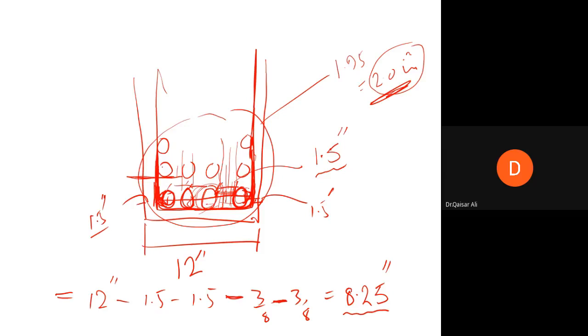Number 6 seems to be very convenient because 5 bars will be required, 3 bars can be placed in one layer and 2 on top of that. Okay, you can also try using more than 2 diameter of bars.